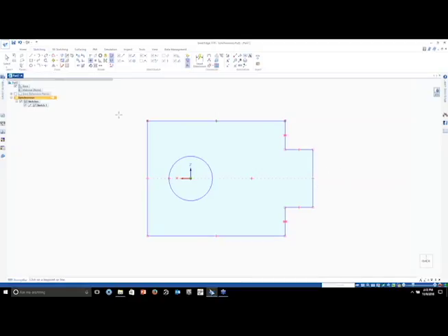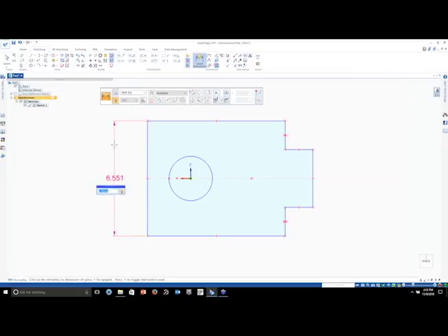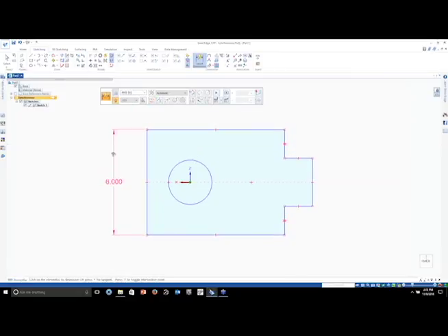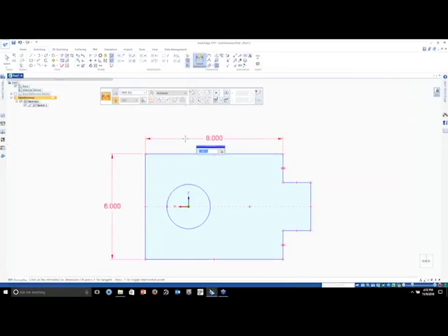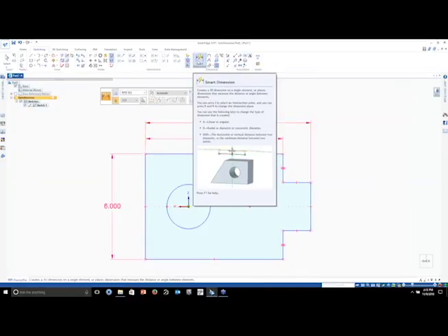All right, so it does several things. As you notice, as you hover over an icon, it gives you a nice little feedback. A little replay video shows you how it works. So we're going to use the horizontal vertical to find a snap point, which happens to be the midpoint here, to my coordinate system endpoint. That keeps that centered on there. And that's really all I need.